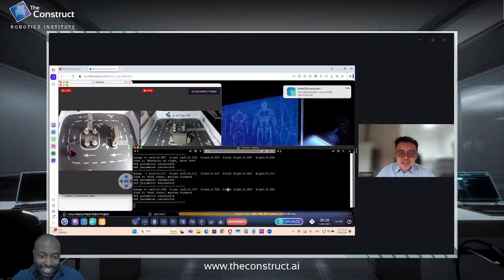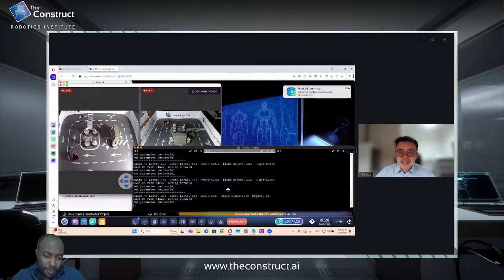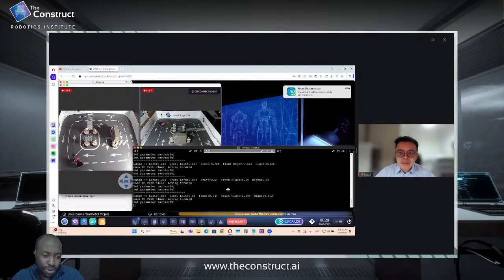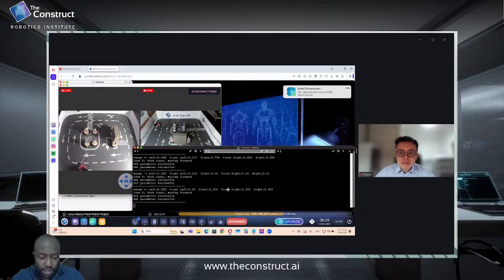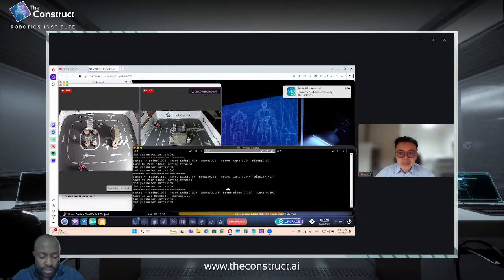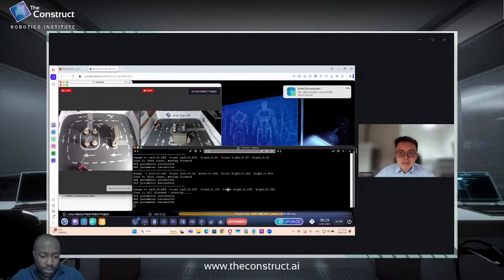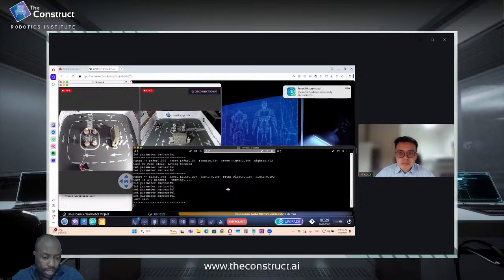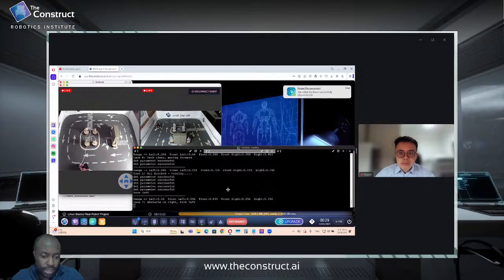All right, so I'll tell you what I'm expecting from you. The reason why you said sleep time to 1, right? Once you set a velocity of 0.1 meters per second, you know that at 0.1 meters per second, your robot is going to go for 1 second and stop, right? Because you make it sleep for 1 second, and then you set it to a different value after that second. So if you set it to an angular velocity, if initially you had set it as a linear velocity, it's going to go forward or backwards for 1 second, and then you reset that value to a different one.